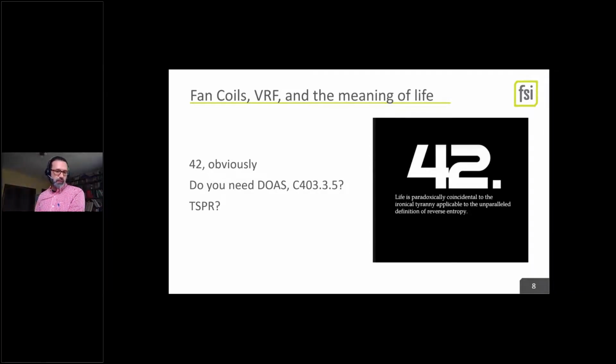And that has to do with the refrigerant and how hard the compressor's working. Again, you got to go look at, did you already have energy recovery? In some cases, you might have. On VRF, we also have to ask, why are you replacing your VRF system already? It's a new enough technology. Did it really fail already? And you kind of got to go looking harder at that.